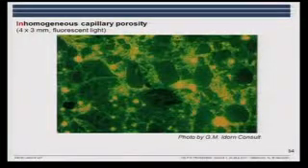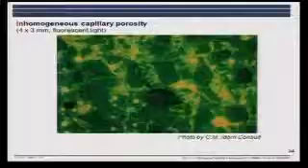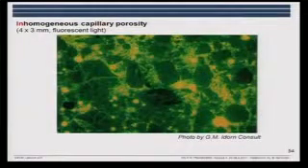Okay, same mix, not so good. We have inhomogeneous capillary porosity. Maybe due to improper mixing, maybe due to problems during the casting. But at least you can see that this is not what you expected. If you model the porosity of this and then use that as information on the rate of ingress, you would not get something which was comparable if you were testing the sample.